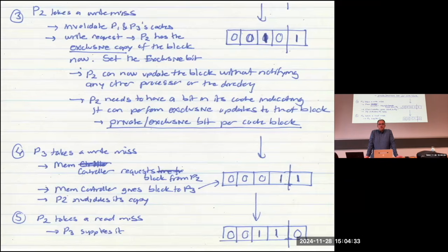Yes, and that processor writes to that. If you read, you don't set the exclusive bit. From the left part, only one bit. So this exclusive bit, in the concept of this example, means that, here the example is better, P3 updates and has the data exclusively. Meaning that when P2 encounters a read miss, the directory knows that P3 has the most up-to-date value of that cache block. So basically, P2 asks P3 to supply that data, essentially.